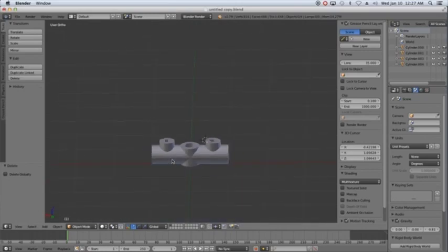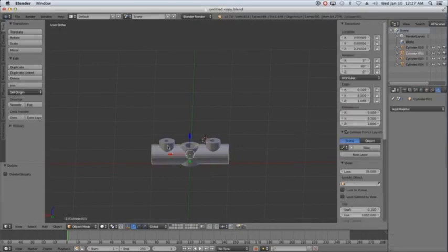I'm going to click on one. All right, now whenever the last one you click on is where the origin for this piece is going to be. So I'm going to use this center thing as the last thing. So click on those two, this, and then that. And then now my origin is there in the center in case I want to do something with it. And click on join. And now this is all joined together in one piece.